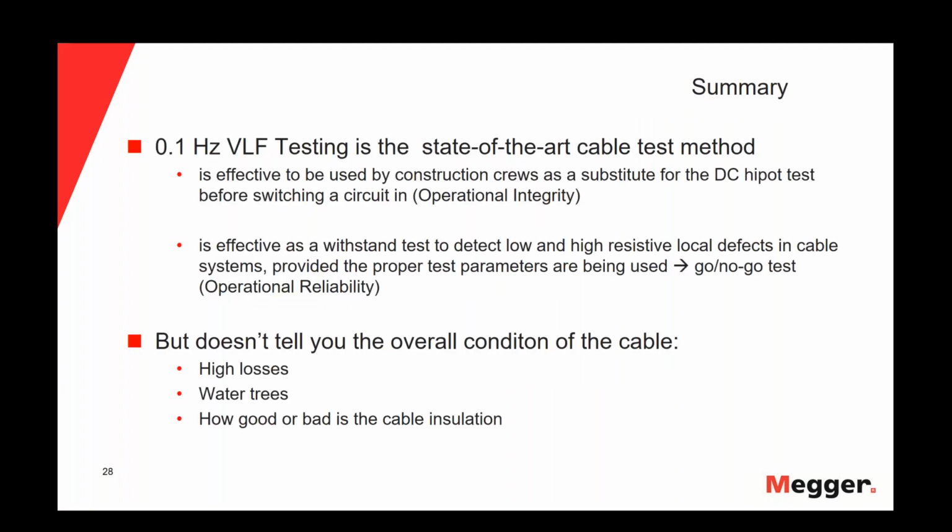So, doing a brief summary of the VLF test, we can say that 0.1 Hertz VLF testing is the state-of-the-art cable test method. It's effective to be used by construction crews as a substitute for the DC hipot test before switching the circuit in. It's effective as a withstand test to detect low and high resistive local defects in cable systems, provided that the proper test parameters are being used.